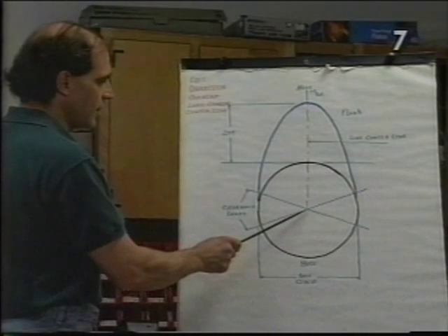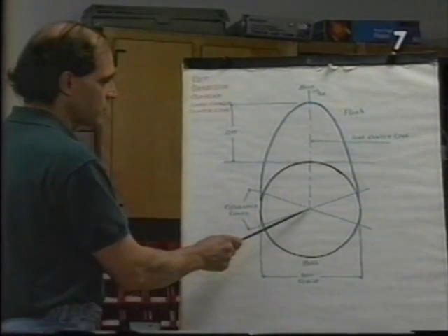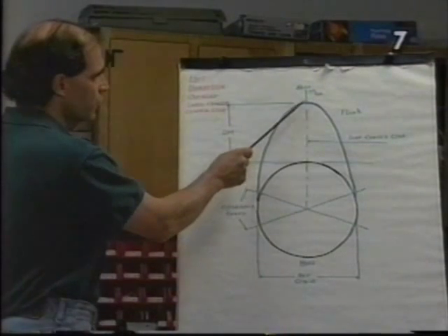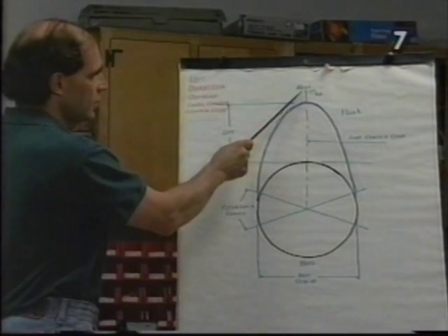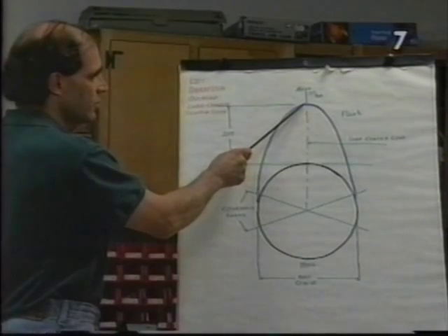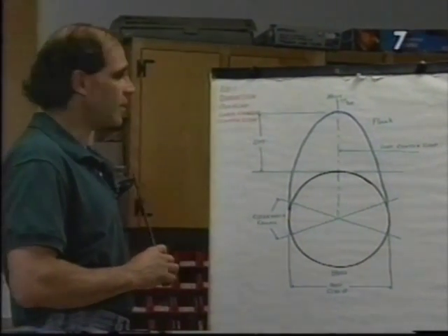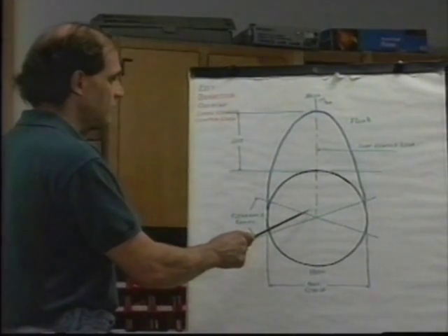The lobe center line is the actual line which will pass from the center of the base circle through the highest point of lift in the nose or toe of the camshaft, and that is what we will wind up using to degree the cam to the crankshaft.